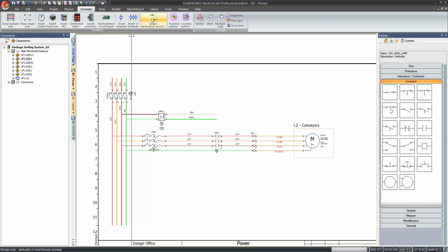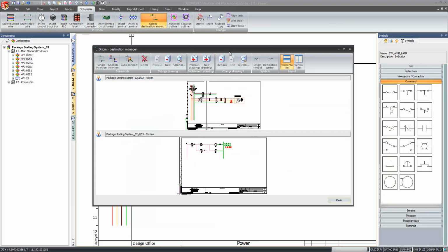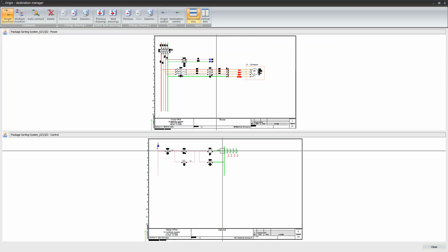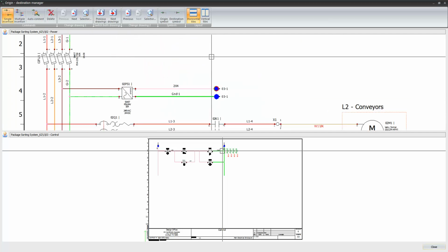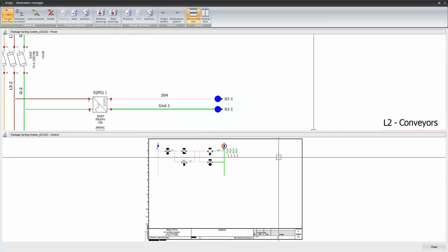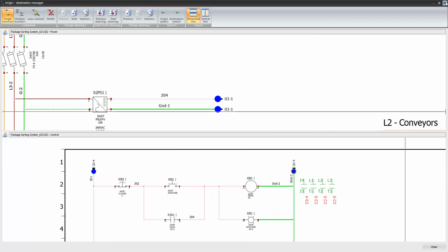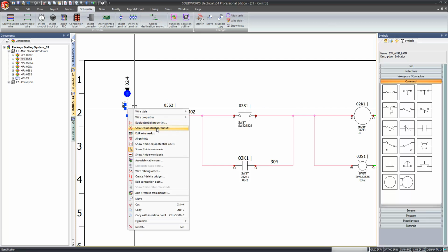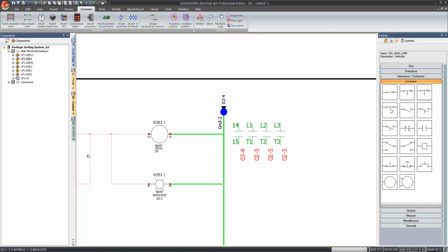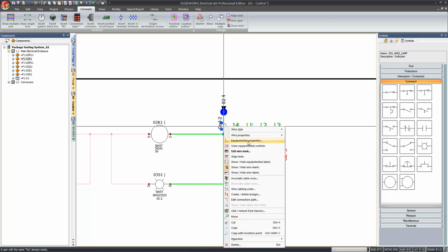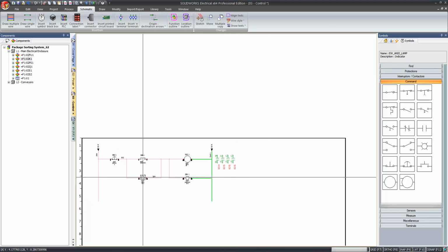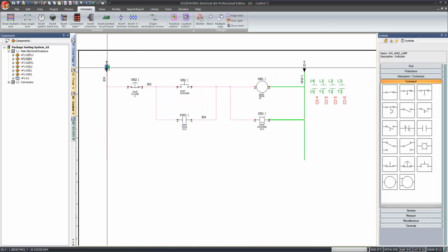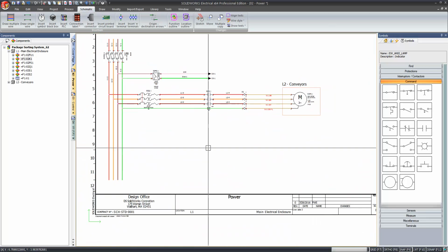We're going to create our origin destination arrows. We want to go from power there to ground here. We get these little blue indicators. And I'm going to pick the control page to solve these, so that way you'll actually see the wires change. So I say solve equipotential conflicts. We'll use wire number 204 there. And solve equipotential conflicts. Use ground 1. So those all updated. And then we'll just double click to go to the power page, show that link.